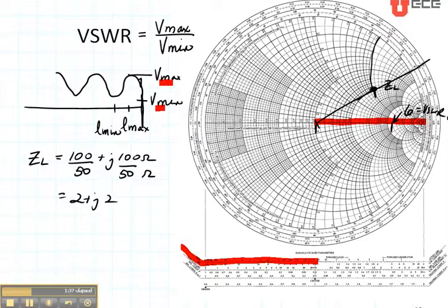Now let's also look down here on this other axis. I'm going to take my center point and put it at the center, and I'm going to measure my value right here. Looks like it's also 6. Now what if I had wanted to find that in decibels? So here is my standing wave ratio, which I can read off in dB.